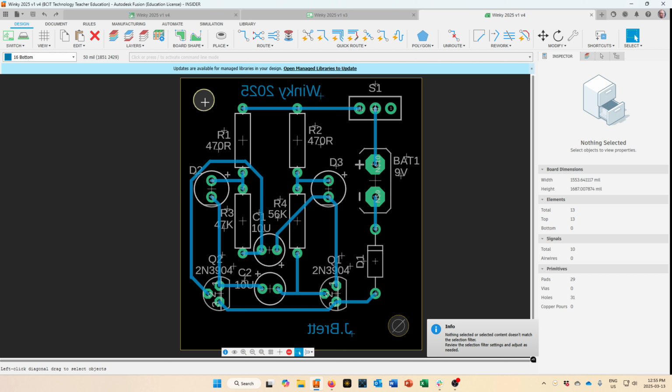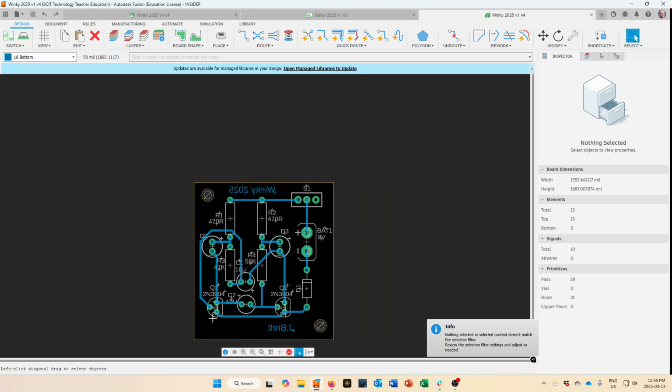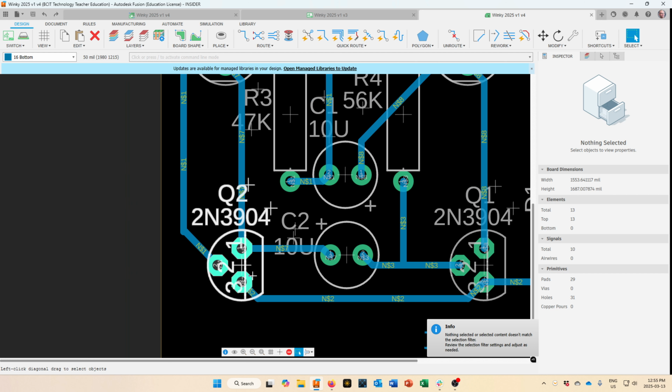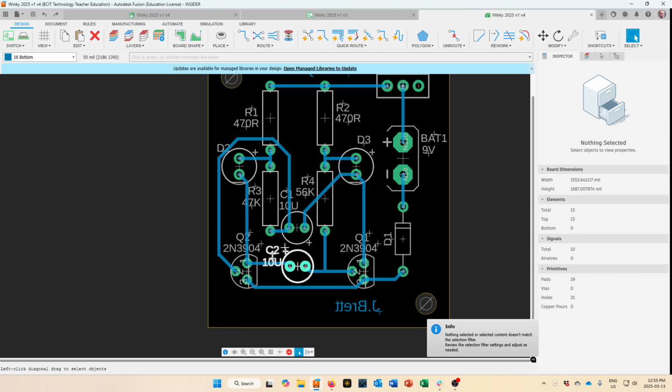And then we'll try and design the board so that a student can actually manufacture it. One of the things I really like about the transistors on this board right here is that rather than having all 3 leads in a row, which is really easy to do, when you put this one back here, it gives you just that little bit more gap for soldering them. So if you're going to make this board and have your grade 8 solder it together, using this design of transistor is probably going to make it a little bit easier as well.